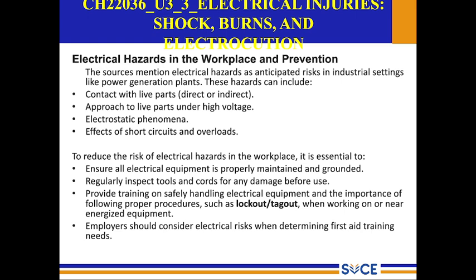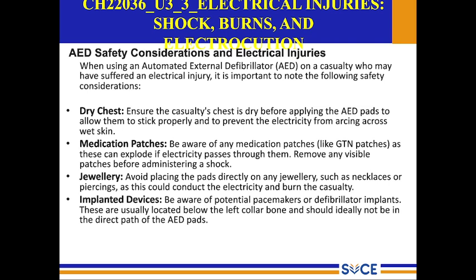How do we reduce the risk of electrical hazards in the workplace? It is essential to ensure all electrical equipment is properly maintained and grounded. Regularly inspect tools and cables for any damage before use. Provide training on safely handling electrical equipment and the importance of following proper procedures, such as lockout and tagout when working on or near energized equipment. Employers should consider electrical risk while determining first aid training needs, and plan well ahead.